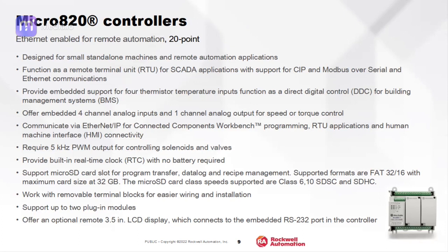Then if you want to give someone a program with some code, you can use the micro SD card for programming as well. You just download in the SD card format, then the customer can load the program onto the SD card, power off the controller, insert the SD card, then power on, and the program will load into the controller. If the end user should not access the code, you can block it; SD program support is available for that.